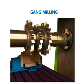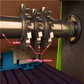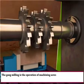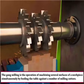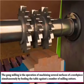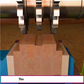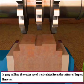Gang milling. Arbor. Side milling cutters. Gang milling is the operation of machining several surfaces of a workpiece simultaneously by feeding the table against a number of milling cutters. This method saves much machining time. In gang milling, the cutter speed is calculated from the cutter of largest diameter.